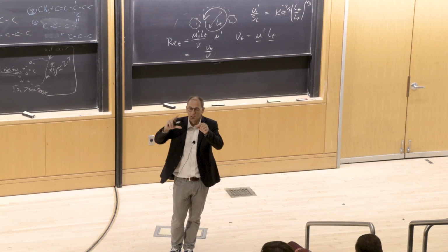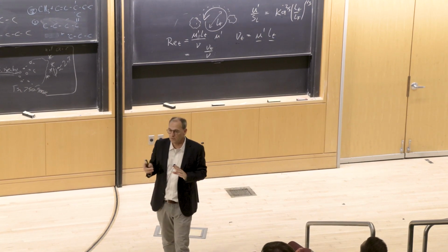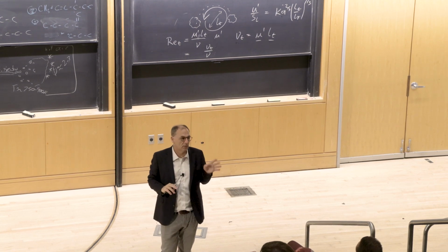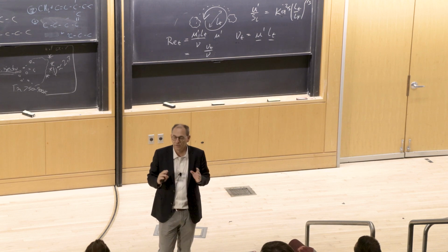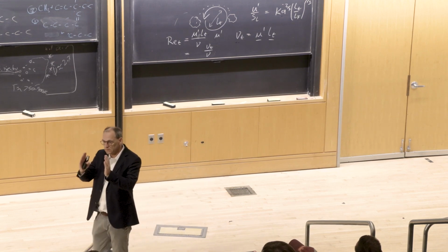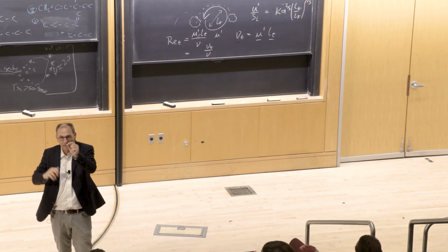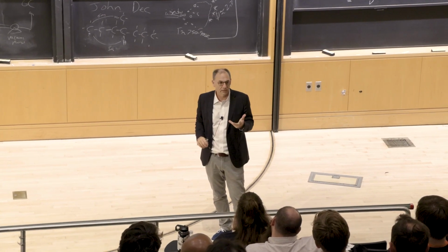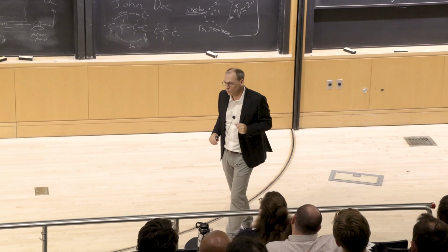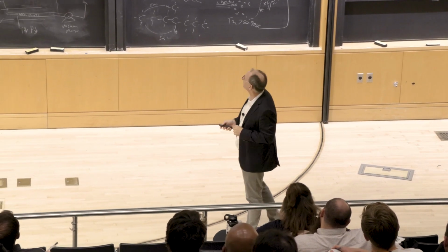When we say larger or smaller, it's easiest to think much, much larger and much, much smaller. So if even the smallest scale of the turbulence is much larger than the flame thickness, then I can treat the flame as infinitely thin compared with the turbulence.